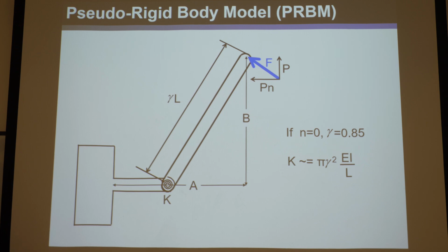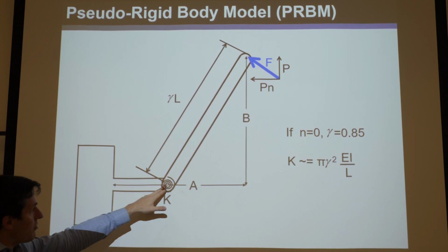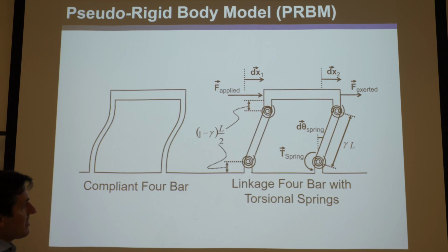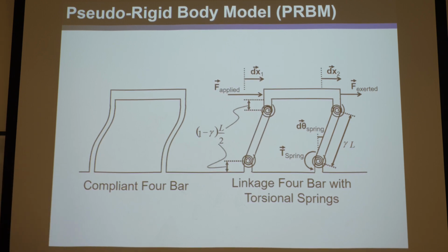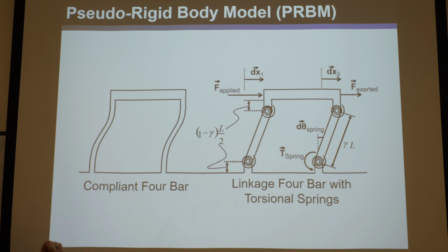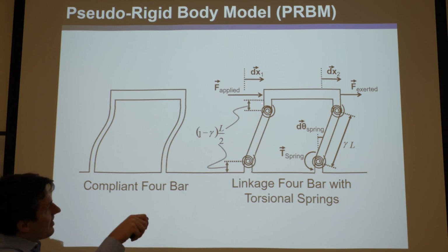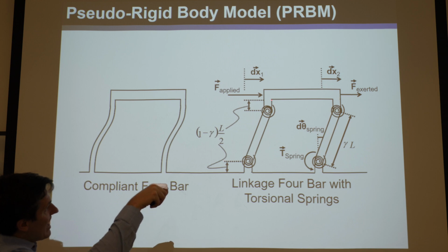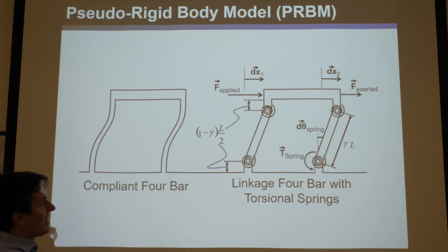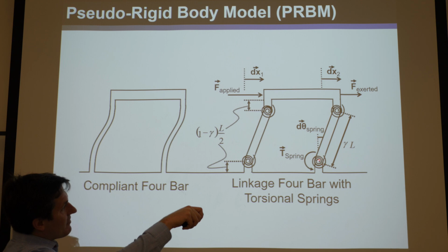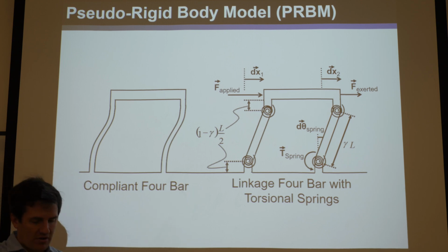And he comes up with these models and these equations to find out where you put them and what the stiffness is. The model has to be kind of different for different scenarios. You can imagine for a 4-bar, it's no longer just a cantilever, it's 2 flexures and everything. And he came up with the equation for this traditional rigid 4-bar where the pins are a certain distance down and these are certain lengths. And then these torsional springs have certain stiffnesses that mimic these.